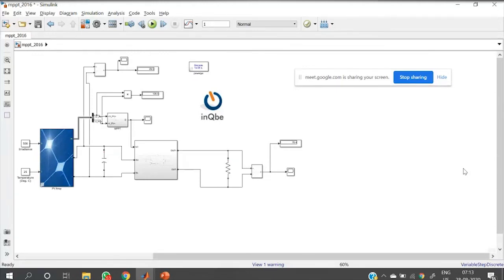Actually, there is a lot of experience and research going on in MPPT algorithms to reduce the settling time under certain variations, and to reduce the oscillation in MPPT P&O. P&O is the least complex algorithm, the simplest one, but for higher applications it will need a more complex algorithm, such as INC, or there are many mixed algorithms, including fuzzy and P&O, to reduce the oscillation. A lot of research is going on to solve these problems in the grid.